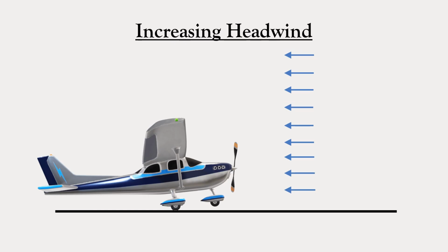An alternate technique for takeoff is to put the airplane into a climb attitude early in the takeoff roll, and then instead of affirmatively rotating as you get to the right speed, the airplane will just fly off on its own whenever it reaches the right speed. That works pretty well in steady winds, but let's consider what would happen if you use that technique in gusty winds.